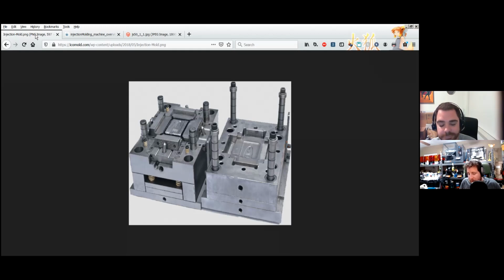With 3D printing, you start off with a raw material. With FDM or FFF 3D printing, fused deposition modeling, fused filament fabrication, the same thing, it's normally a roll of filament. This material is melted at very hot temperatures. Actually, we all joke that one of the hazing processes to being a true 3D printer is getting burned on a hot end. Currently there is our Fusion 3 F410 running. I do have the lid propped because it gets a little too toasty in there.